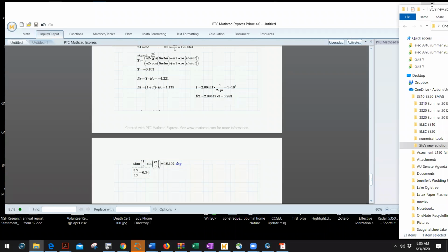That means when I move for that problem, I had the normalized impedance equal to 1 plus J1, right? And when I take 1 over that, I get 0.5 minus J0.5. You can check me on that. I think it's about right. Isn't it, class? That's right.